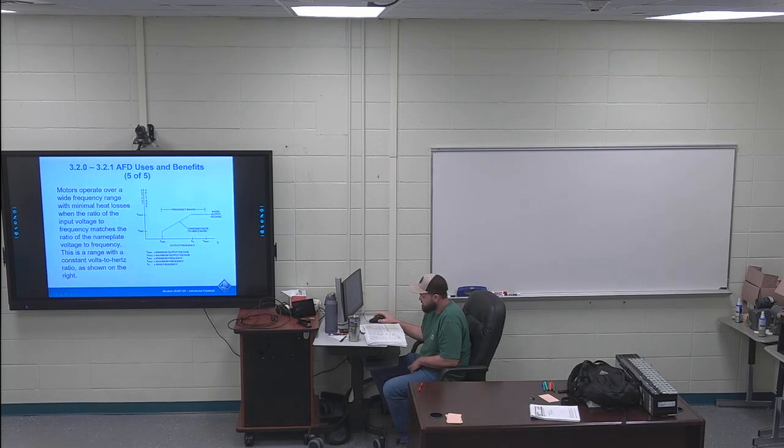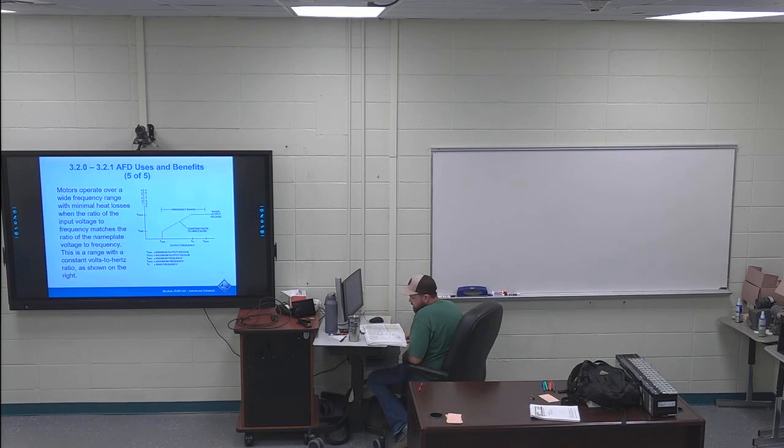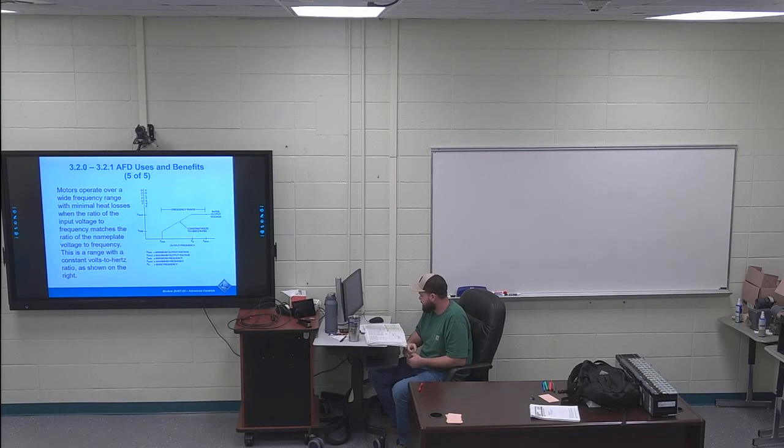I have a couple of questions come out of there. Going along with that section, the last bullet point, which is on page 29, is highlighted. Matching the adjustable frequency drive to the motor design is important. As shown in table 6, NEMA design A, B, and E motors are best suited for use with an adjustable frequency drive, although an adjustable frequency drive can be used with other motor designs. Those 3 are the most common though, A, B, and E.